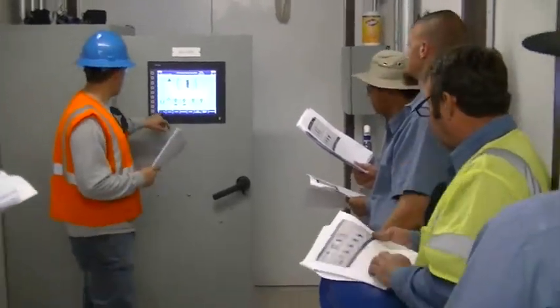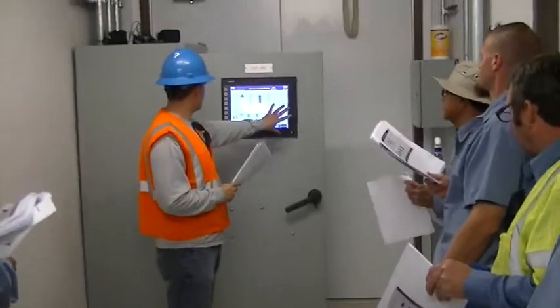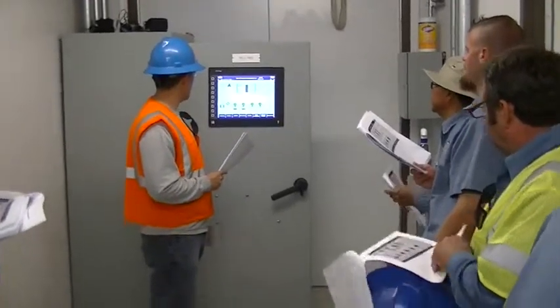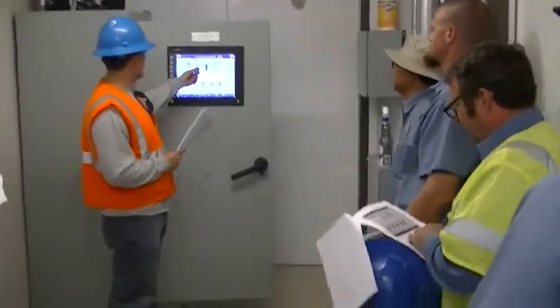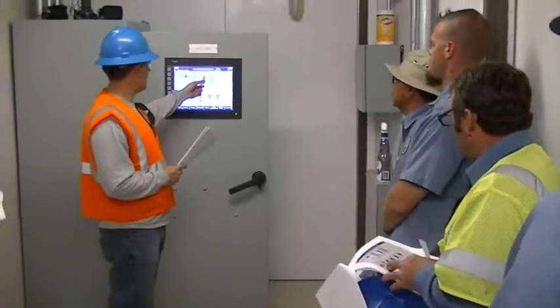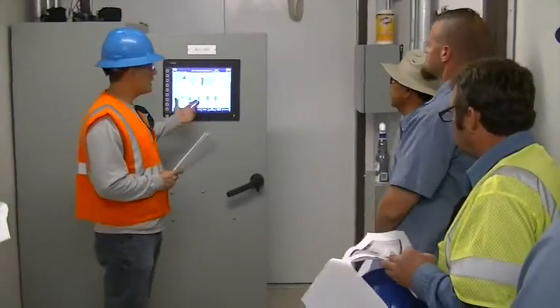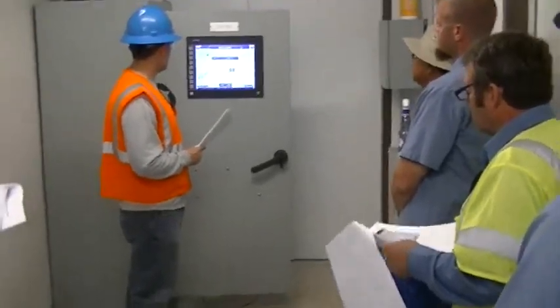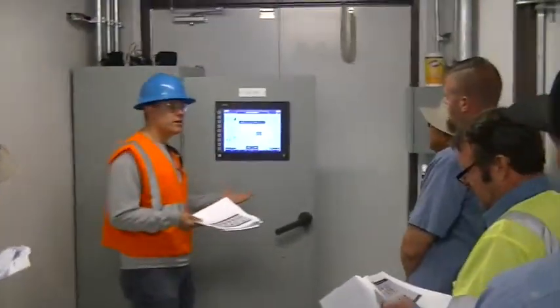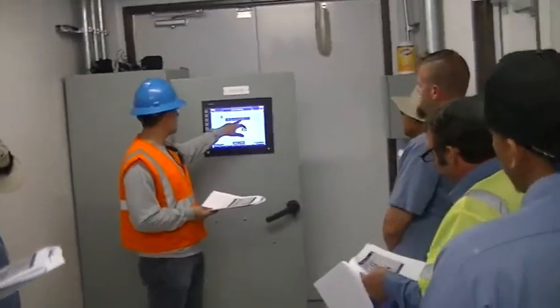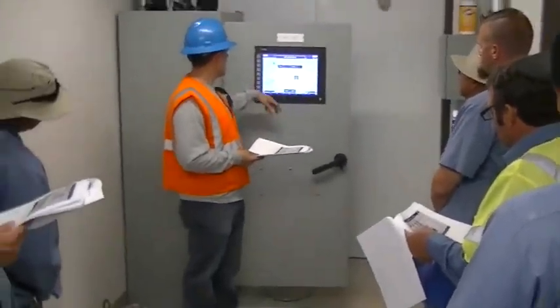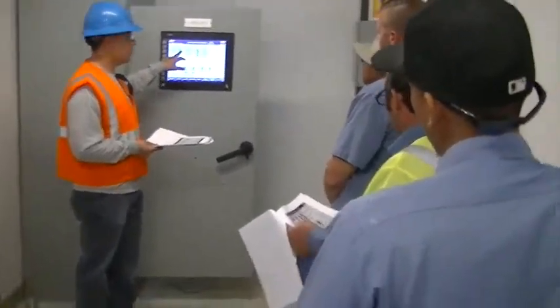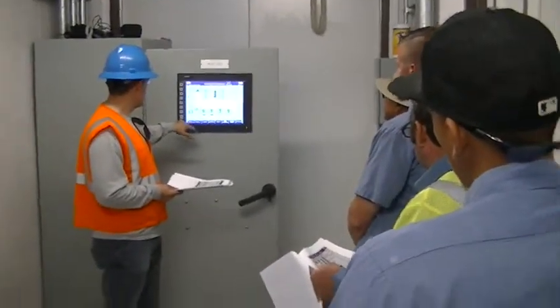All right. So that basically covers this front screen right here. Obviously, when we go over, you've got your level, and then you've got your physical representation of the water in the tank. Your MOV, that's the manual operated valve. So you have a manual control over it, or you can have it in auto. I'll show you where those set points are here in a minute.